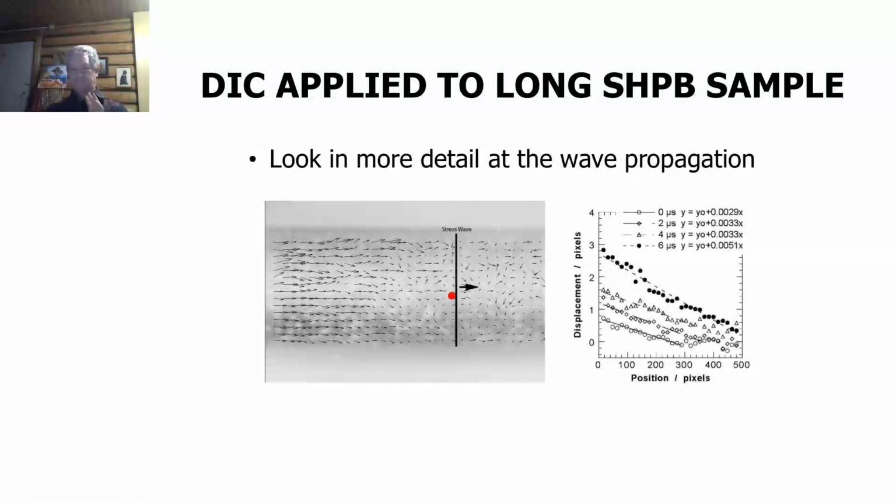If you're looking very closely, if we were able to see grain by grain and the binder between them, we would see that non-uniformity of strain. But when we look out across the whole sample, we're seeing hundreds, if not thousands, of those interactions. So the average effect, and you're highlighting the key point, is we can see volume conservation in the sample, and that's how we got the lateral strain from the simple Hopkinson bar equations.